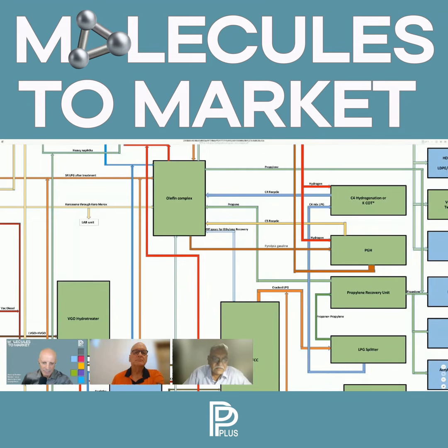The other part is the raw water source. If the source is fresh water which is available from a river and one can get a clearance for that, that is fine. But when the requirements are very large, for instance, of the complex which we are talking about, the requirement would be huge. So in certain cases, we have a mix. You could source from multiple sources. One could source from river.